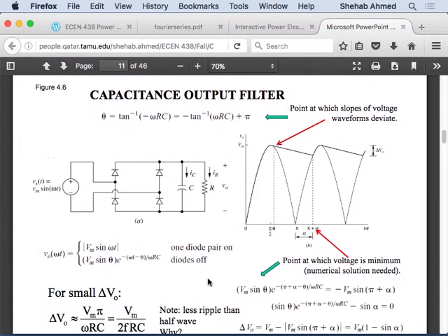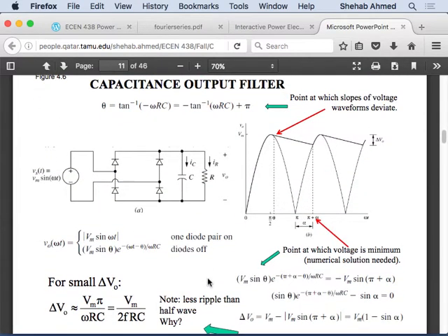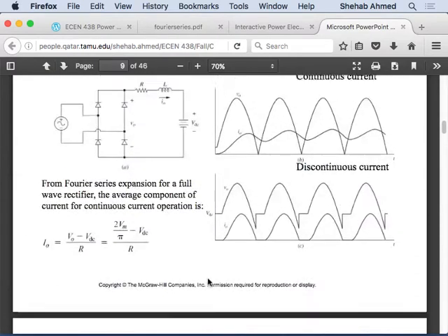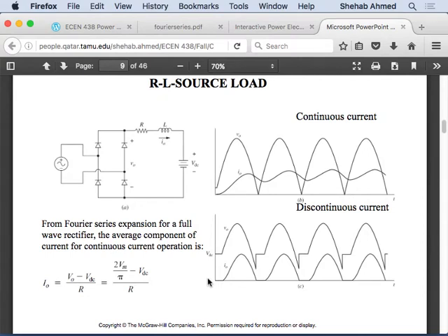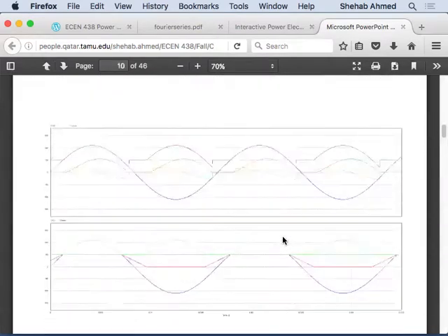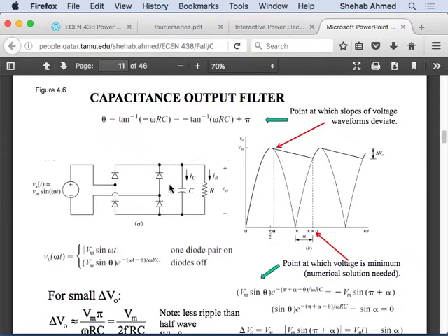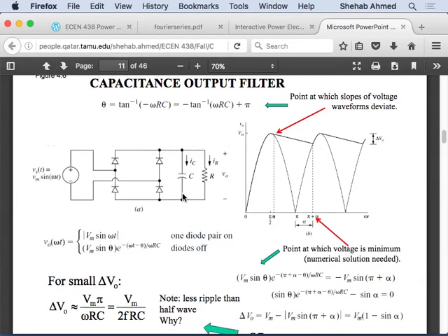And now, for the output capacitor case, similar to the half-wave rectifier, the objective here is to do what? We want to create DC with low ripple. How do you do that? You cannot merely do that with the circuits we've had before, because generally they have huge ripple. From the minimum value of voltage to the maximum value of voltage is very large. So how do we deal with ripple reduction in rectifier circuits? We would typically put either a capacitive filter, or, as you will see later, we may add some inductance to it as well.